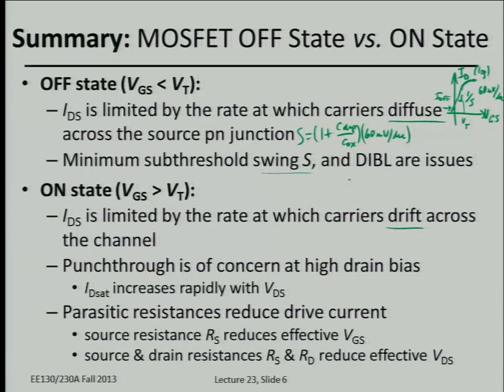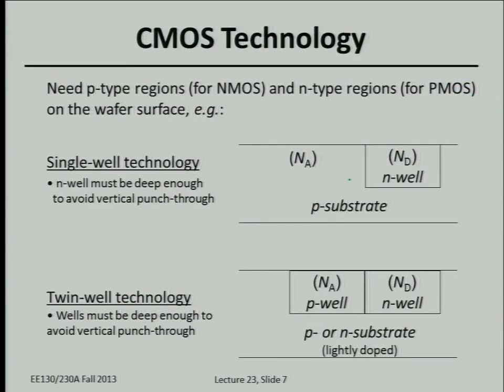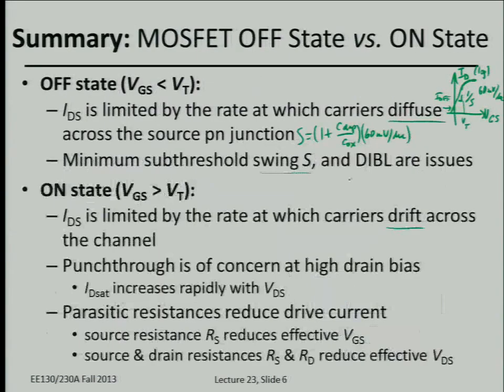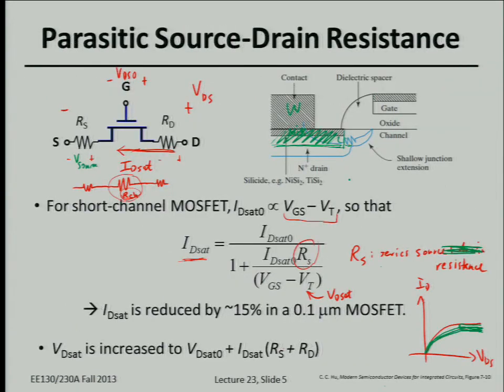So you just have to keep in mind that there are some non-ideal things that can limit on-state resistance, and you want to be able to operate with reasonably large VDS without having current flow out of control of the gate. Okay, so that's punch through. Punch through is not good simply because the gate really can't control that current very well. It actually occurs beneath the surface of the silicon. Are there any questions just generally about these qualitative phenomena that occur in modern day transistors? No?